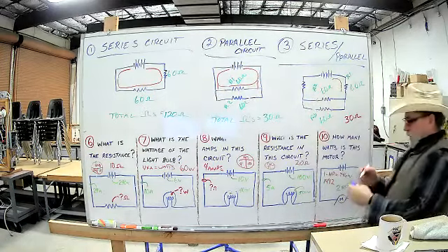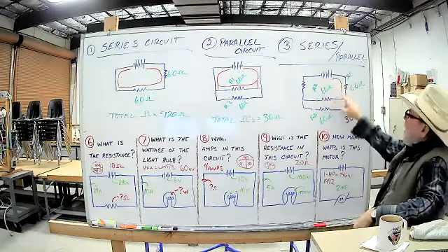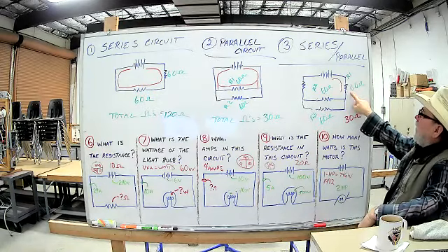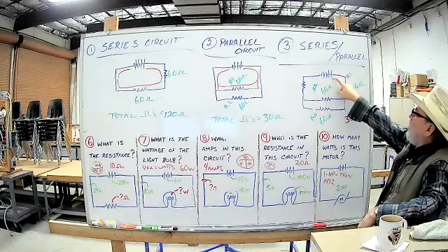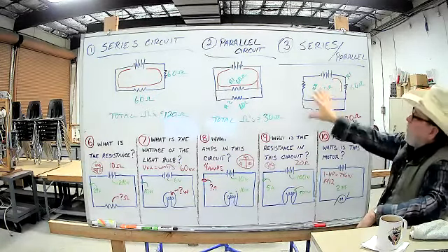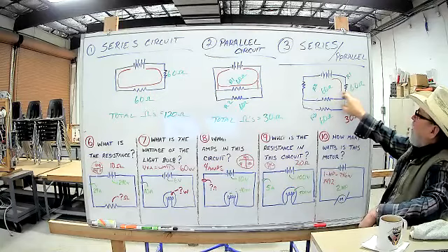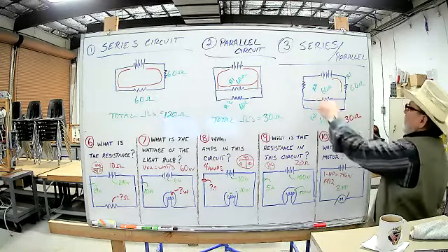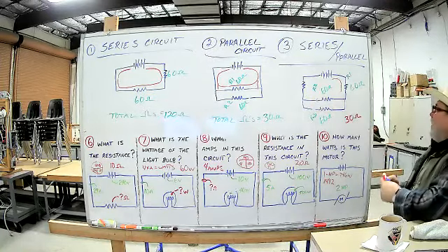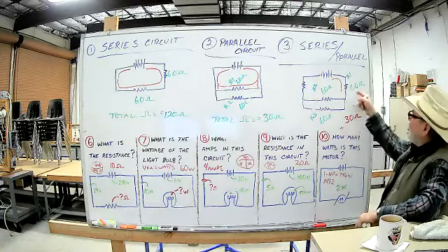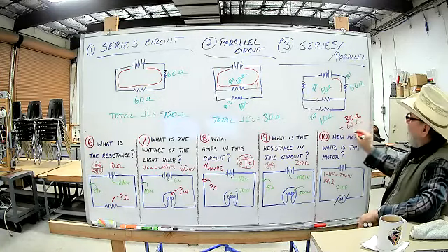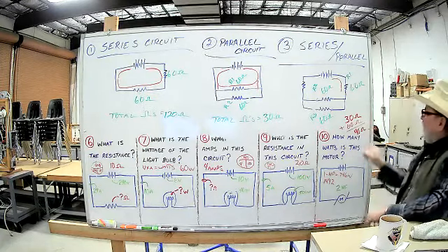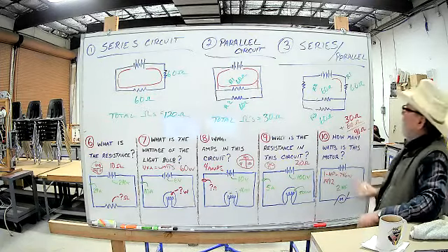We take it out. Now, we also know that everything that flows through these two has to flow through that one. So now we have one path. It goes through here, and then it goes through these two. So this is a part that's series. So when you have this 30 ohms, which are these two, in series with this 60 ohms, you add them. You add those up, and you're going to get 90 ohms. 30 plus 60 is 90.